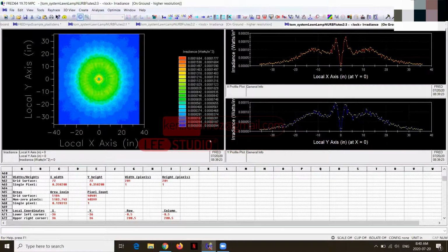The default setting in Fred is actually ray splitting, where when a ray comes into a surface and there's a transmission and reflection coefficient and/or scattering, multiple rays are created to generate each component. That is also possible on the GPU, or you could switch to using Monte Carlo, depending on the situation. It's your choice. So the GPU ray trace can handle both of those techniques. This means both sequential and non-sequential are possible with MPC? Well, in both cases, we're talking about non-sequential.